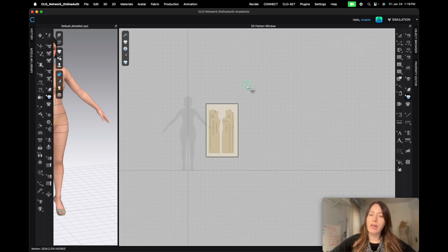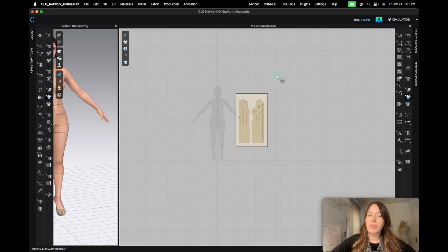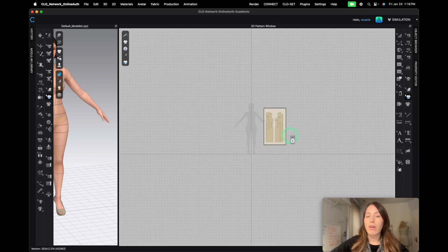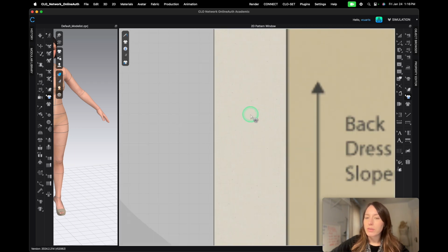So click and drag, and that is panning. But zoom is one of your other three navigations, and you can sort of use zoom as panning when you're trying to work quickly. So zooming out a bit and then repositioning your cursor to the area you want to zoom into is very helpful and quick.